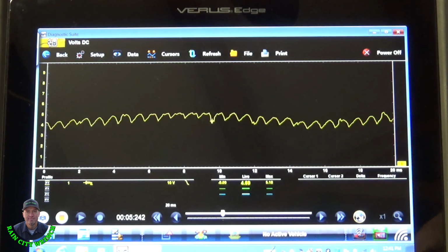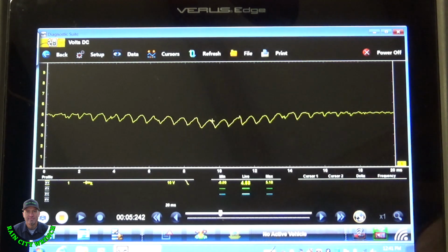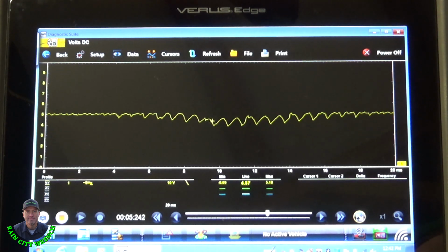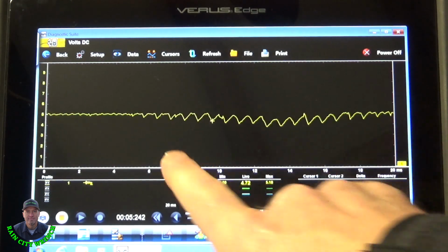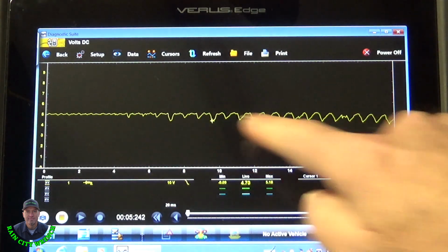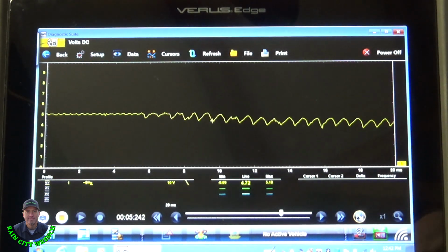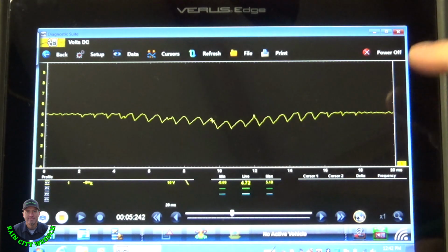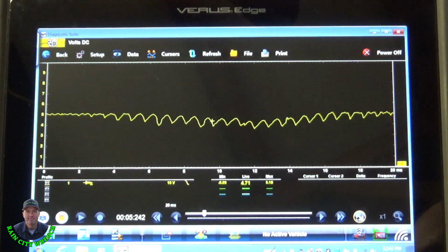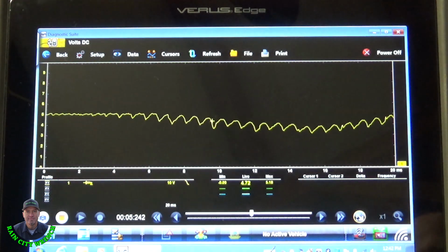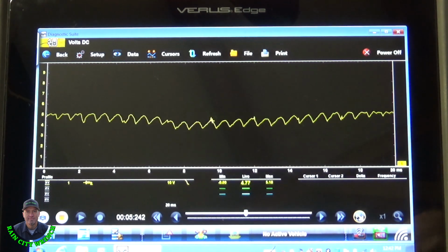So to keep this running, to do the ignition system, and I've got, looks like headlights on, tail lights on, to run everything, it's pulling 47 amps right now. And then you can see the diode pattern in it too. It looks almost identical to a fuel pump pattern, actually. If you see some nasty spikes on this, I saw a Dodge once, just sawtooth, big nasty spikes, and it had a bad diode in the alternator. So this one looks great, and it's 47 amps.